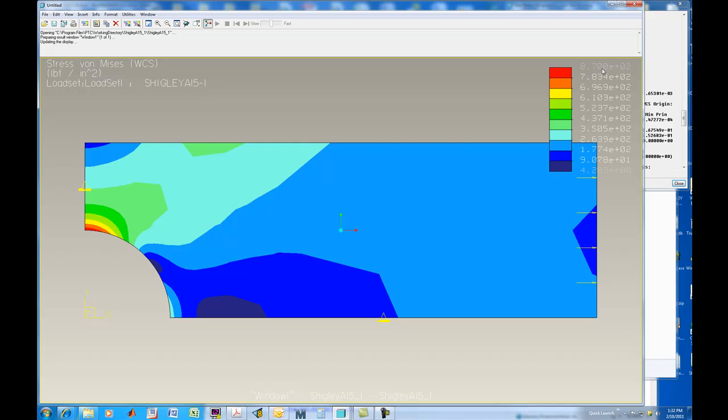I'd say we are definitely within an acceptable precision or an acceptable accuracy, and so we could stop it right here. About the only other thing we could play with is, since it converged, we could allow it to go to a higher order by reducing the error term in the analysis box. I think I'll stop this one right here, and you've seen a plane stress element being run to calculate the stress concentration of a hole in a flat plate loaded under axial tension.